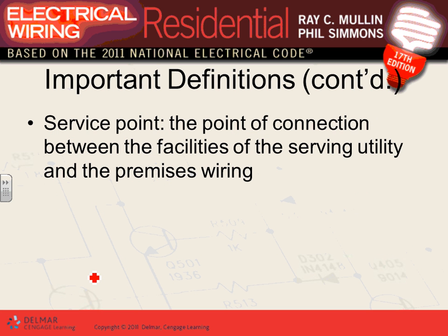So let's go to the service point. There is a term called service point, the point of connection between the facility and the service utility. That's the point of coupling, or the demarcation point. It's the point where the utility brings their cable and your cable meets the utility cable. That's called the service point.